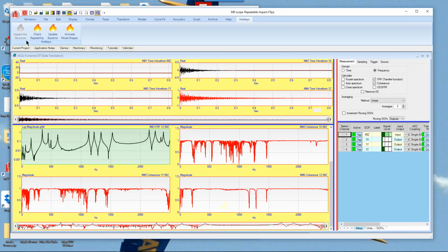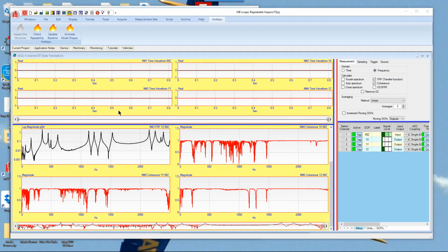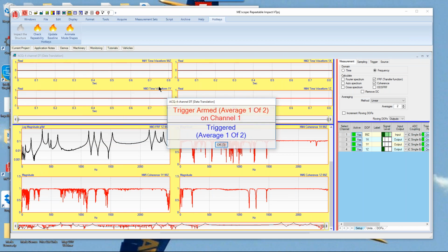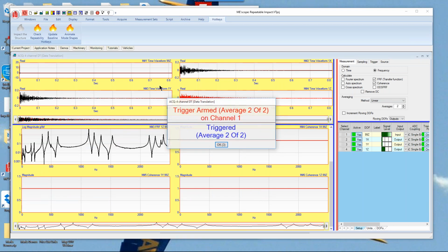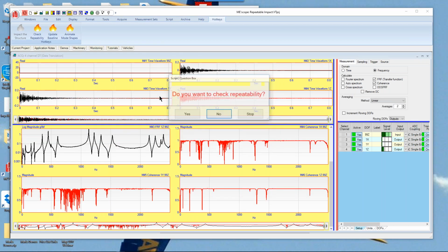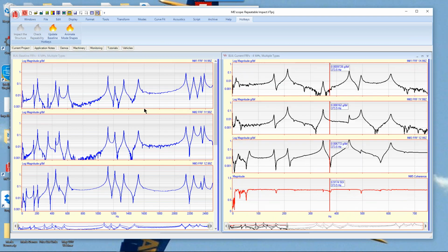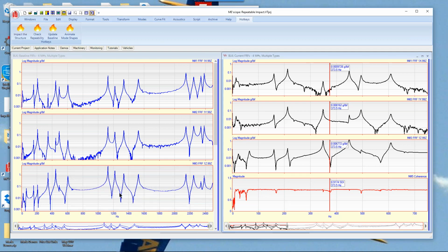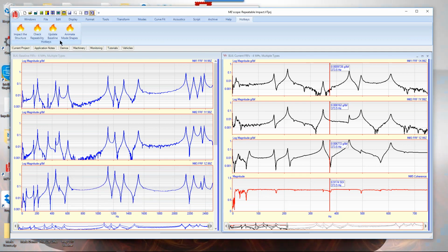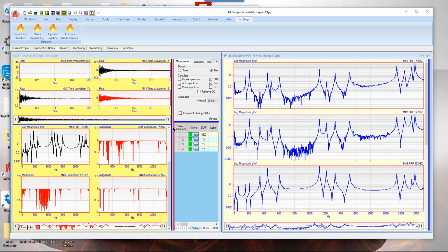Let's do it one more time. And I'll go back and hit close to where I saved a baseline, and okay, let's check repeatability. There I hit back in the same place again. Now just one more check of this. It says update the baseline. So I'm going to take this data that I just measured and call that my new baseline. Let me do that. And so that's going to transfer that data over and save it away in my baseline